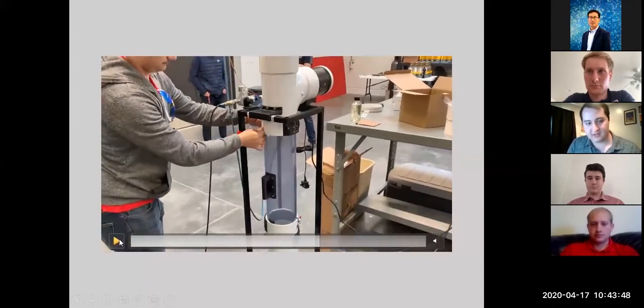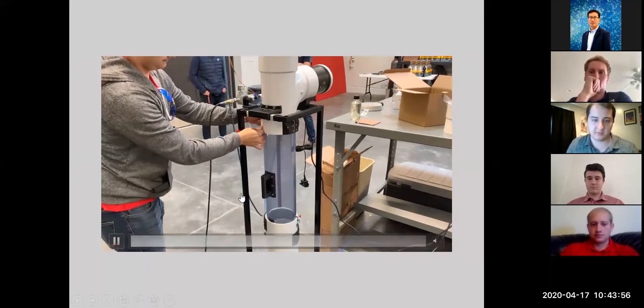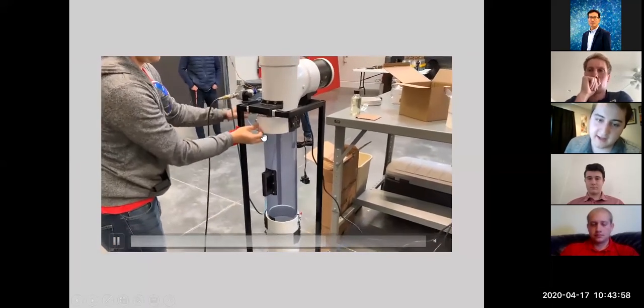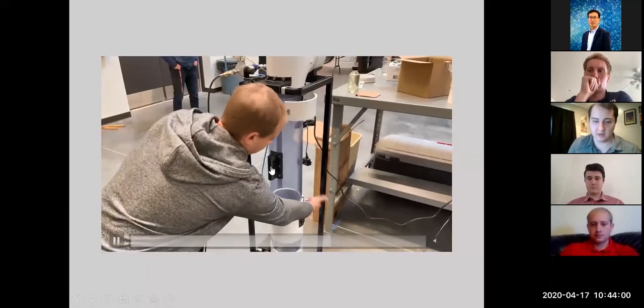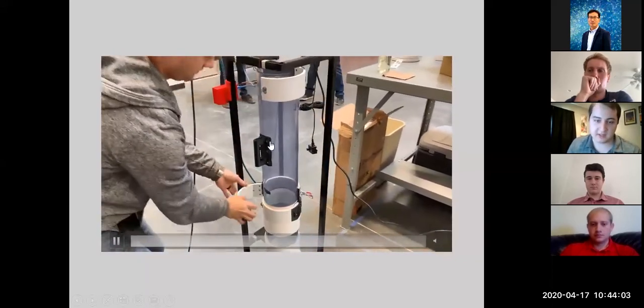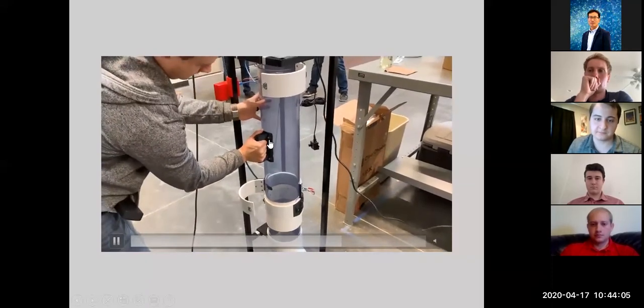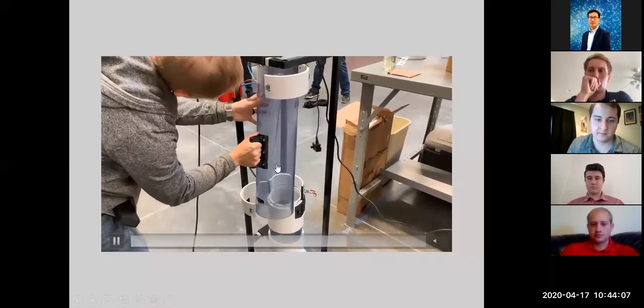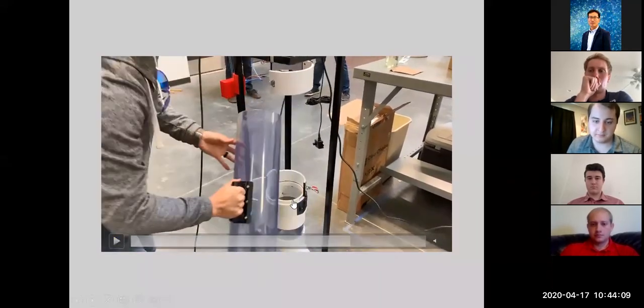For changing the actual pipe to clean it, you just pull up on that pipe that Jerem just pulled up on, and then you undo this toggle latch and then the bottom toggle latch. We 3D printed a little handle here, so it's very easy to just pull right out, like so. Then you end up just pulling this off, and you can clean the entire thing really easily where it matters.